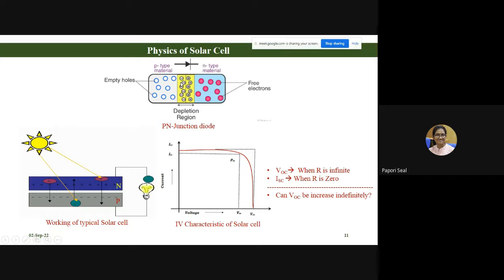Now they become stable. When someone gives off an electron, they become positive. So these are your positive space charge ions near the n-type material. In n-type material, we have an excess of electrons, so they want to give up this excess because of the repulsion within themselves. So they gave up to the p side. Now the p side wanted to receive an electron, they received. Now they become stable. Whatever they wanted to give up and receive, everything is accomplished. So here, because they gave up an electron, they become positive. Because they received an electron, in p type they become negative. But they are stable now.